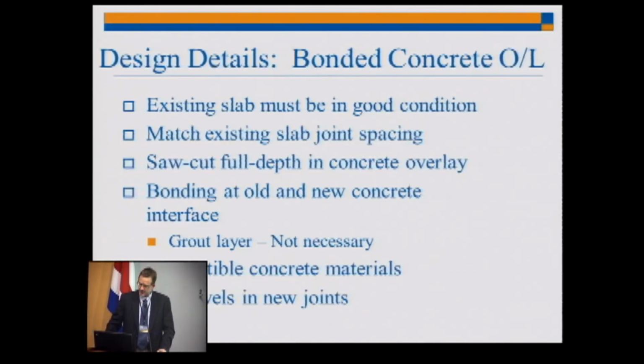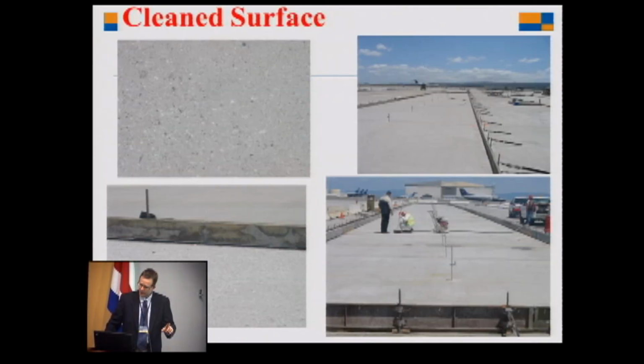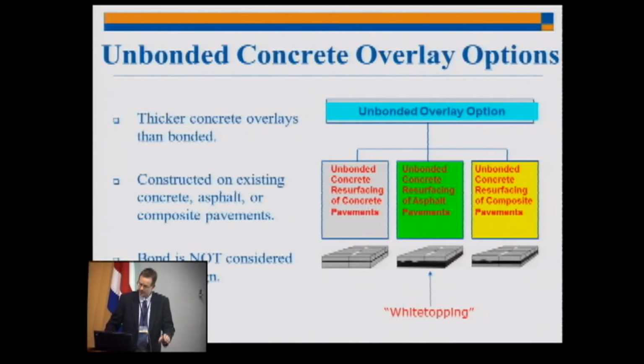I'm going to skip this and just go quickly to my last. These are bonded overlays, but that's not applicable. Just a couple notes on unbonded overlays, which are probably less applicable here, but for maybe high volume roads. The key here is that your structural design for unbonded overlays are going to be very thick. They're probably going to be in the order of 20 centimeters for heavy volume roads. So you're going to have to deal with elevation problems with your roadway, bridges, ramps, and shoulders.